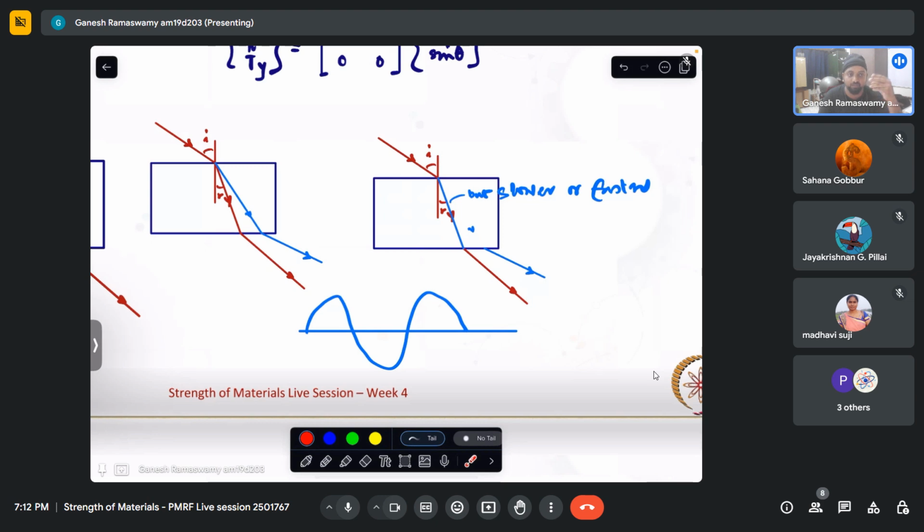So when we impinge light on it, it will split into two light vectors, but with different velocities, which will start forming some patterns. And it turns out that the phase lag between these light vectors is directly proportional to the stress. So the more we stress it, the more light gets split into two, with more velocity difference, more phase lag, and a different color emerges essentially when we impinge light.